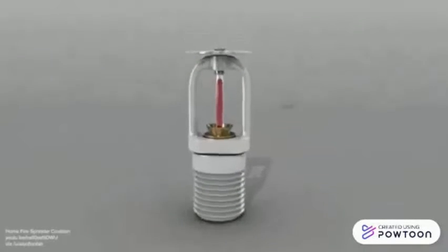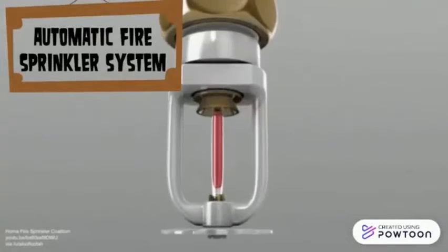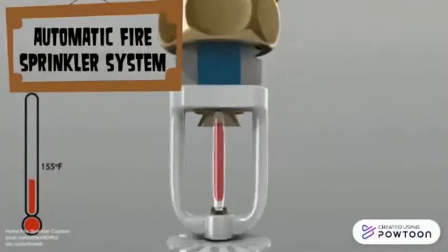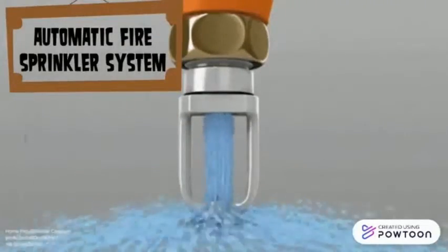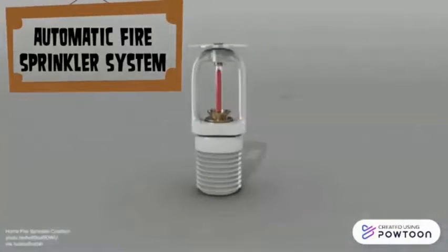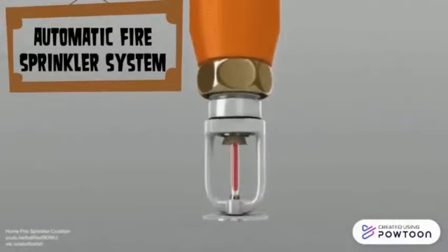The sprinkler is a nozzle attached to the pipe network and mounted just below the ceiling of the room. Each sprinkler has a small glass bulb with liquid in it. This bulb usually blocks the flow of water. In a fire, the liquid in the bulb will become hot. It will then expand and destroy the glass bulb, removing the obstacle and causing water to spray from the sprinkler.